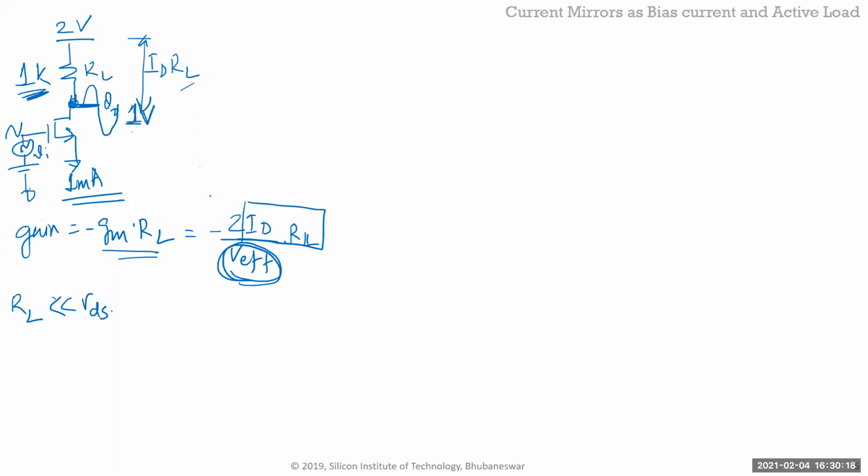So the DC and the AC gain are not decoupled. They're actually coupled. In our previous example, the R naught was to do with length, right? And ID, but the IDs were canceling because the GM was proportional to ID and RDS was inversely proportional to ID, so they canceled, right? So it was only proportional to L. So I can bias the output at any voltage, and any bias current, independent of it. That's desirable, right? Because then it allows me to pump more current, work with a smaller device, or pump very little current, work with a larger device if it is a slower amplifier.